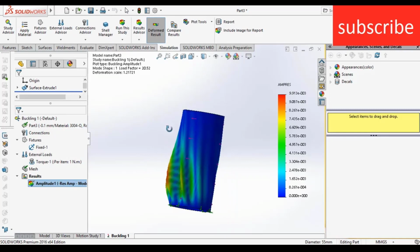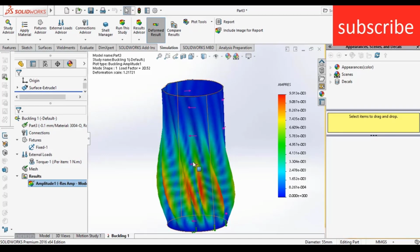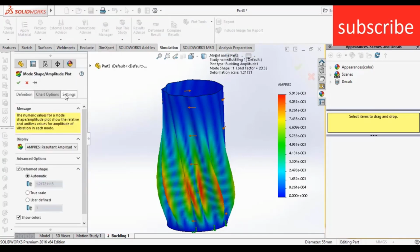Here you see that the displacement is quite large. The reason is that when you do a simulation, Solidworks shows the deformation much higher than normal. For example, go to edit definition, click here, and you see it's automatic and the scale uses 1.212. Now click on user defined, and enter 0.5.